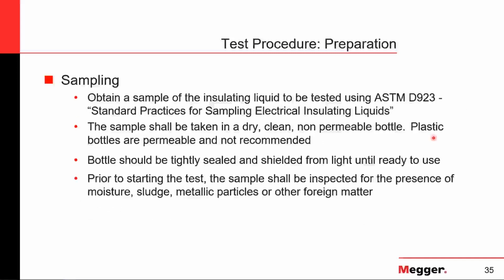After you do that, let's say you brought your equipment from other location as well as your sample. So before the beginning of the actual test, make sure you allow enough time for both the sample and the vessel to reach ambient temperature or room temperature between 20 to 30 degrees C.